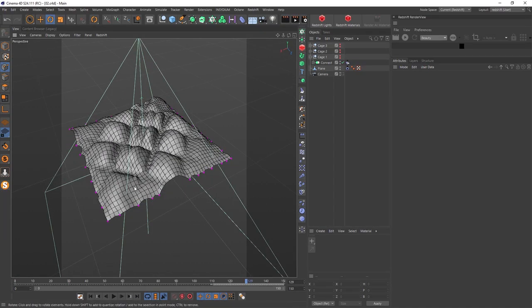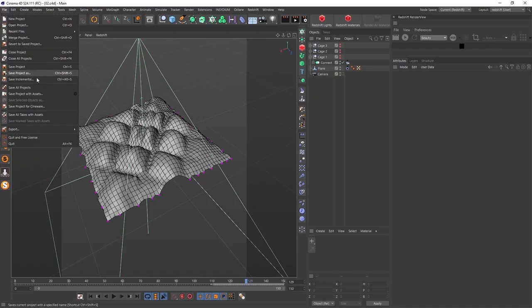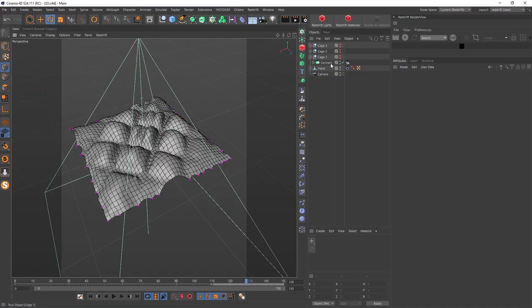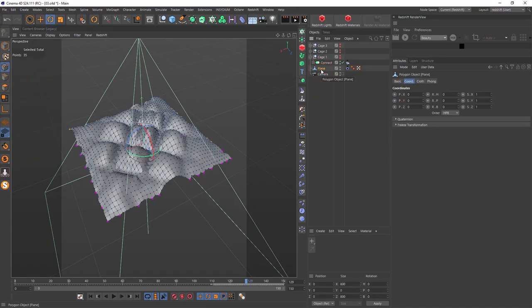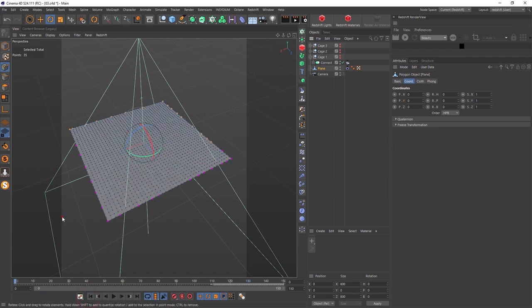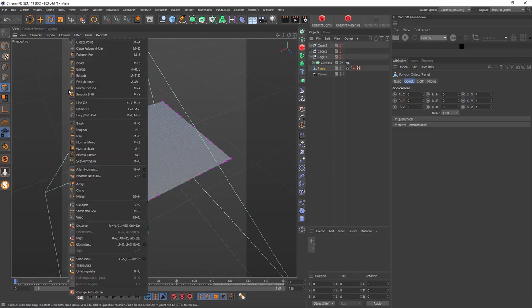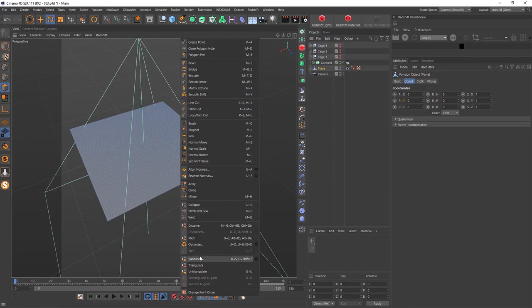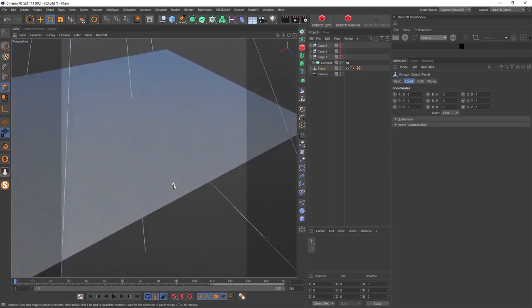So what we have to do is create a new copy, going to play. We have everything going right as we want. Unselect everything, go into plane to polygon mode, right click and set subdivide 2 times. It creates a very dense net.